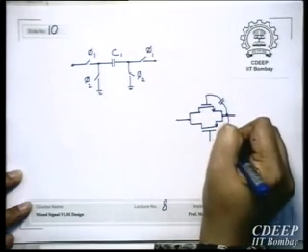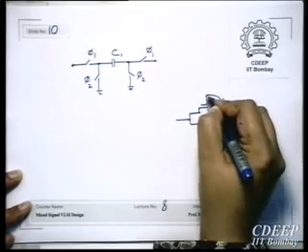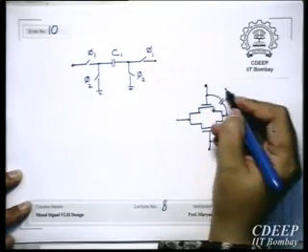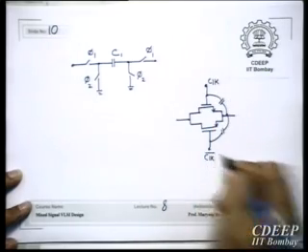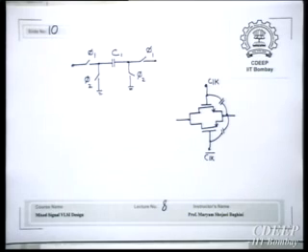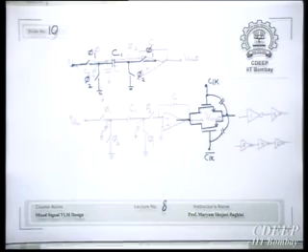If you can match these two capacitances properly, which is usually difficult, then this also will solve the problem of clock feedthrough. That's why the first method is preferred, putting in the dummy switch.